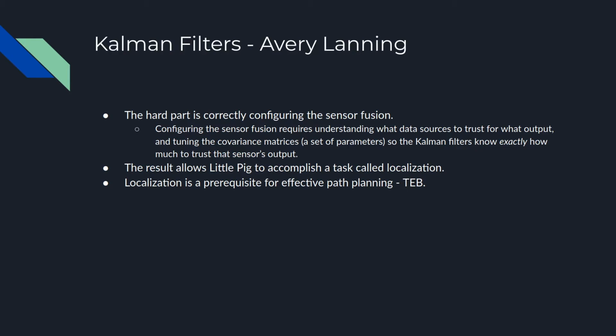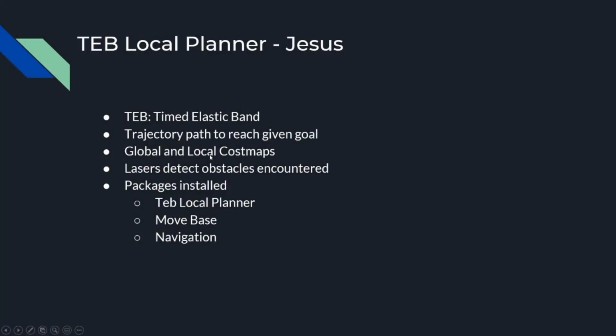Hello, my name is Jesus Villagrana, and I will be giving you an overview about TEB Local Planner and how the package was implemented within our project. TEB is time elastic band that will create a trajectory for Little Pig when given a navigation goal to reach.